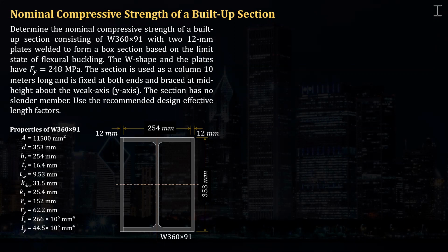Let's go on to determine if the buckling is inelastic or elastic. If it is inelastic, then we use the formula Fcr equal to 0.658 raised to Fy over Fe, times Fy. If the column is elastic, then we use Fcr equal to 0.877 Fe. That can be determined by whether KL over r exceeds 4.71 square root of E over Fy. So we need to calculate KL over r.